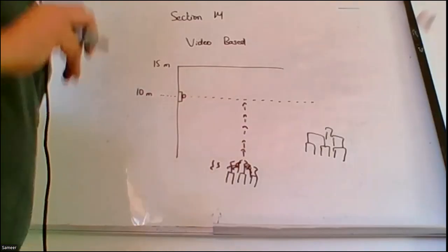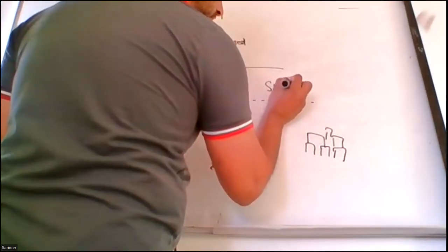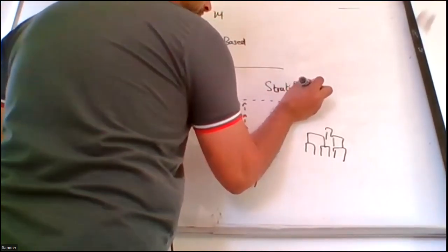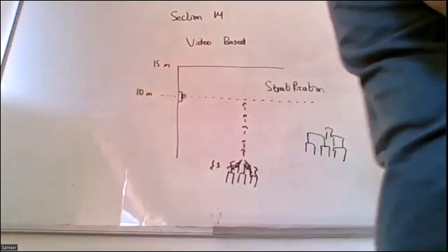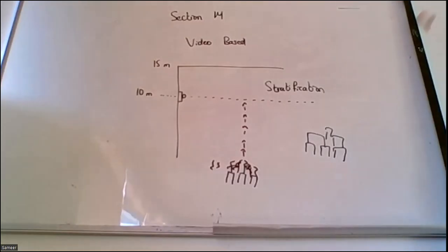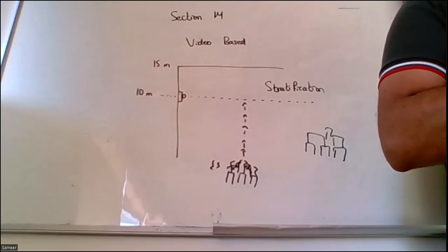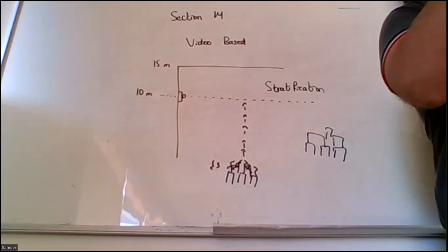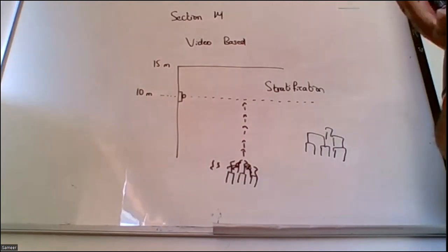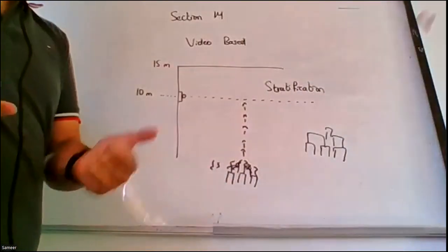Now this phenomenon is known as stratification. Whenever you read NFPA 72, it will always say that the detector should be placed in an appropriate location to avoid stratification. And what does it mean to avoid stratification? It means that you have to avoid delay. So the detector should be placed for timely operation to avoid stratification. What is stratification? This delay is the stratification phenomenon.